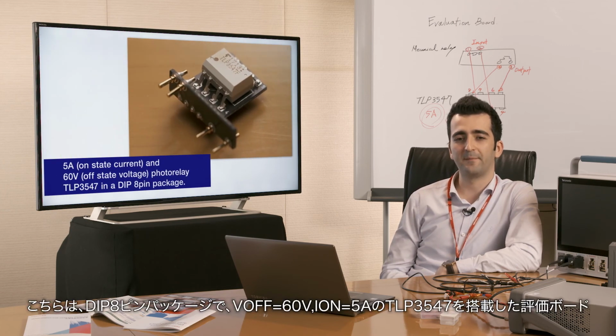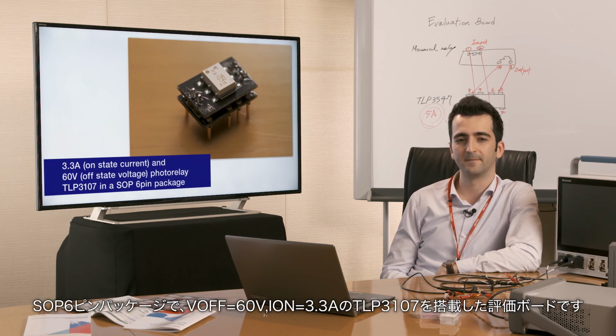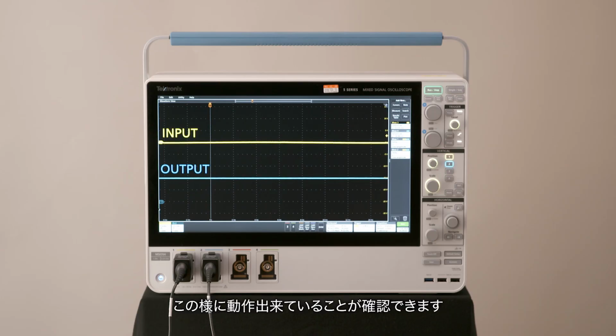This one is a 5 ampere on-state current and 60 volt off-state voltage photorelay, TLP3547, in a DIP 8-pin package. And this is a 3.3 ampere on-state current and 60 volt off-state voltage photorelay, TLP3107, in a SOP 6-pin package. The input side of the coil is between pins 1 and 2, and the output side is pins 3 and 4. You can directly replace your mechanical relay with this evaluation board to test your design. You can see how it works here.